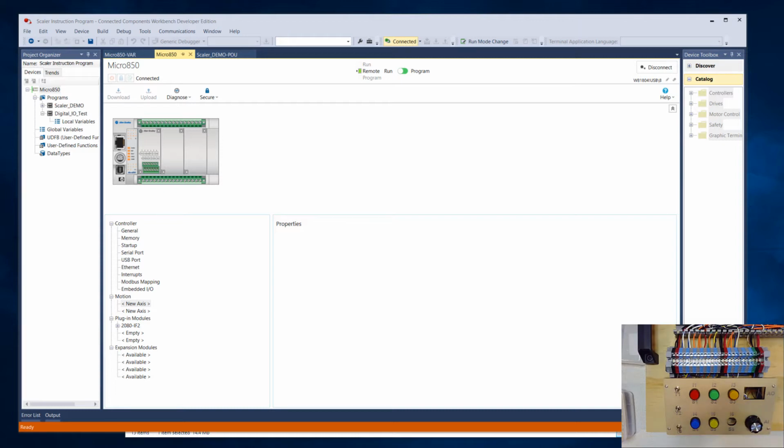But let's say we wanted to use that to vary the time of the flashing lights like I used in that example program. Our on-off time in that case was in the range of maybe 100 milliseconds up to 1,000 milliseconds. So how do I take my 0 to 60,000 number and get it into useful units like milliseconds or percent speed or RPM, something like that? There's a number of ways we can do that. We can do it with just basic math instructions.